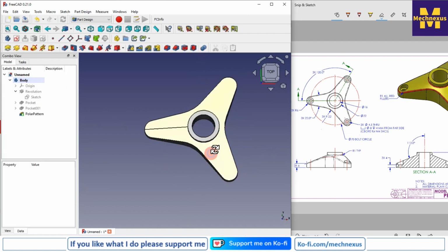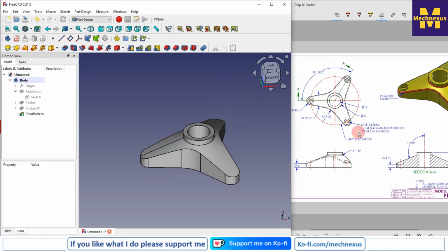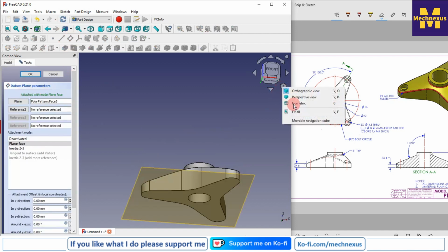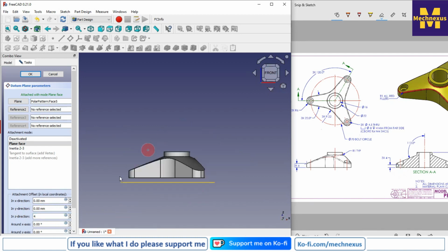Now we have to make this counter bore holes. So for the counter bore holes, we will select the bottom face and click on the datum plane, click on the isometric view, and from the Z directions, so here is a 4 mm, so I will create a plane at a 4 mm. So here I will give the minus value and I will say OK.